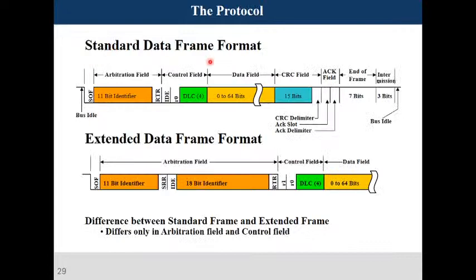Okay, what are the standard data frame and extended data frame formats? How is the frame format? Start of the frame, already I have mentioned. Then the 11-bit identifier, remote transmission request, IDE and reserved bit, DLC, how many bytes were transmitted, and the CRC field, like that.